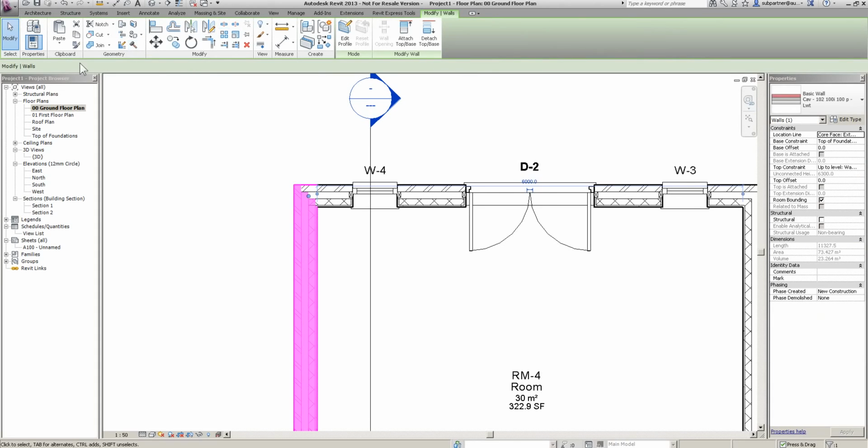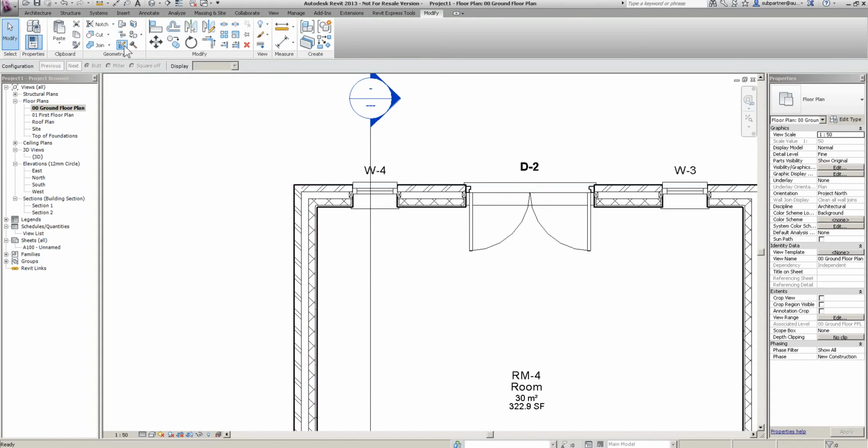Select anything to bring up your modify tools and come over to where we've got wall joins. When you select a wall join, it will show you how the walls are butting into each other, and they are set to a butt at the minute. We can set it to a mitre, but I actually like to do it properly. I'll go to a butt, and then I'll just press next or previous, so that now this wall's butting into this. Basically, because this wall here was butting into this wall, and this wall's going up, there was a little gap at the top of this wall.